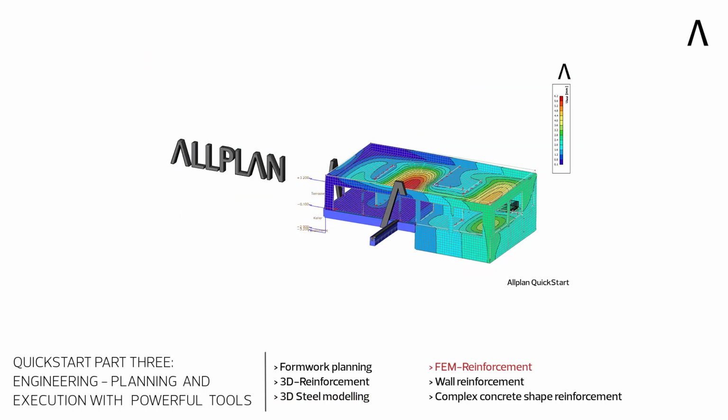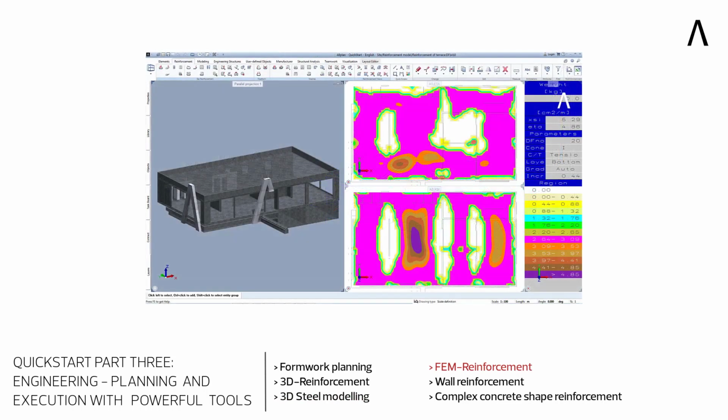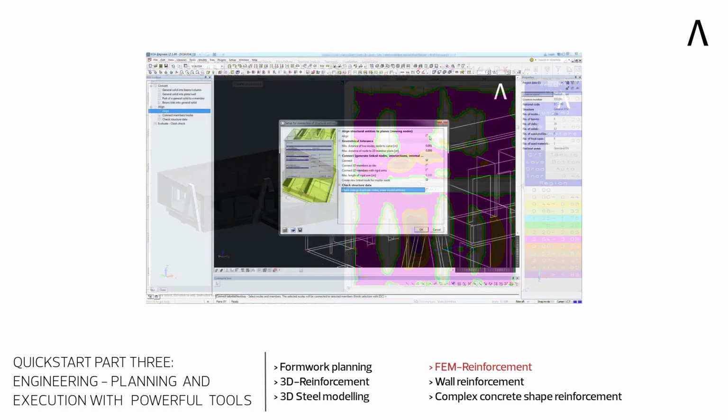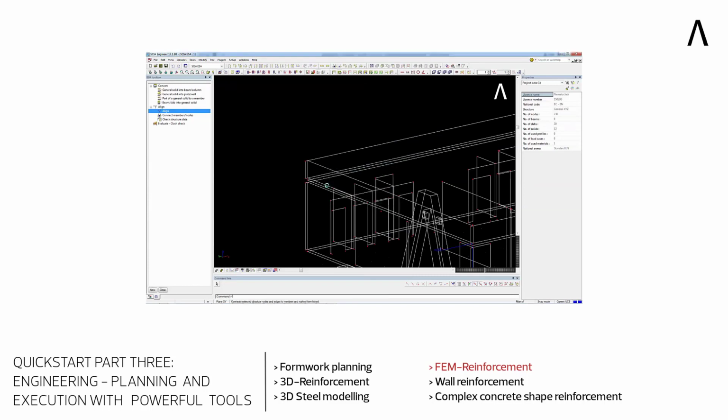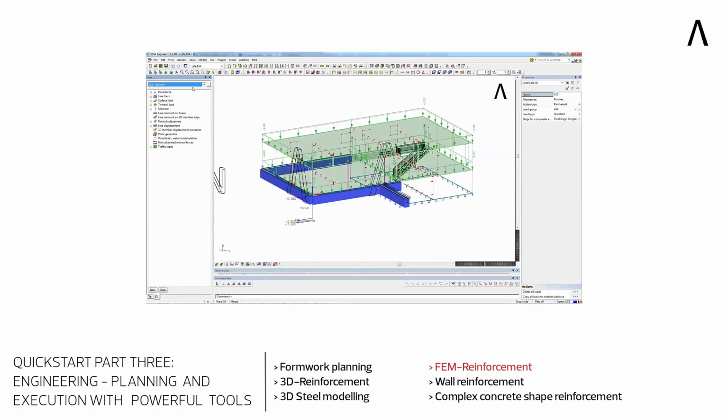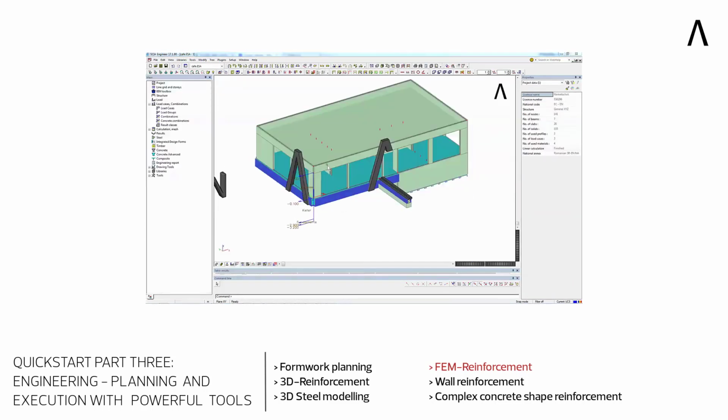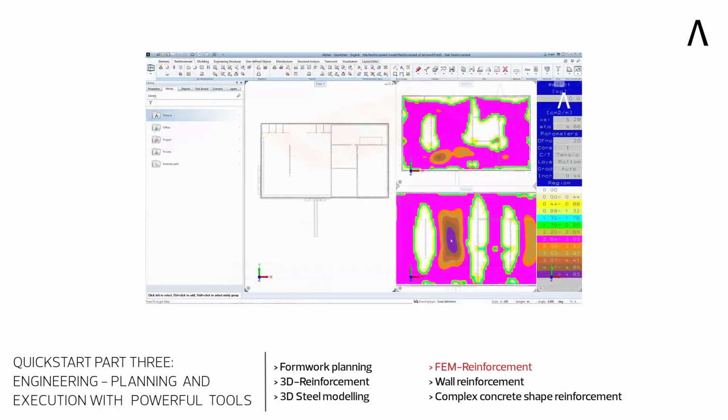The building model created in Allplan can be converted into an analysis model in SIA Engineer via IFC. The design in SIA is based on Eurocode and the results are exported to Allplan as ISO lines of the required reinforcement. The final reinforcement in Allplan is based on the theoretically required reinforcement. The system can also provide an automatic solution containing all details with corresponding bending lists.